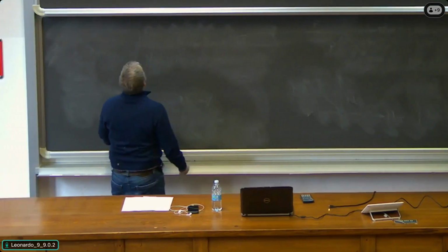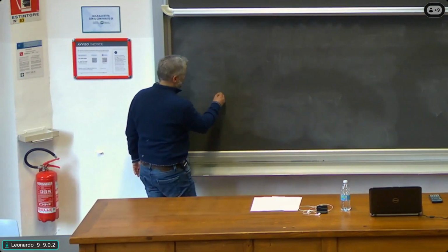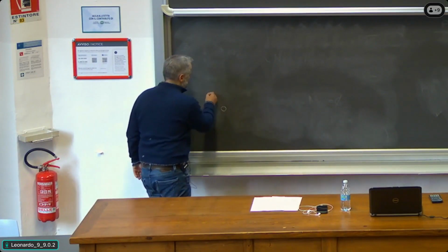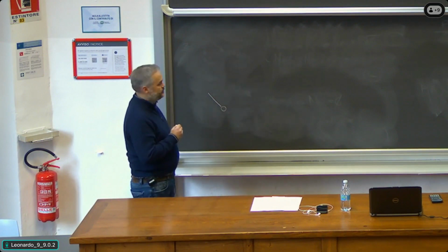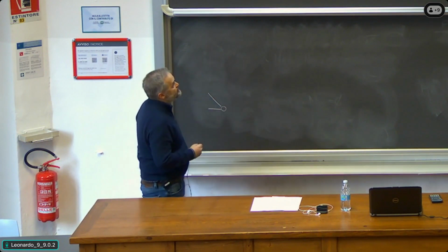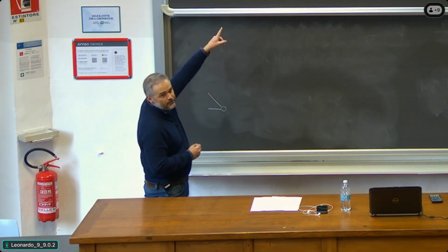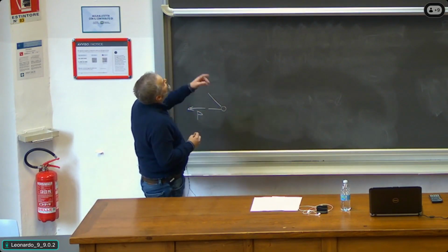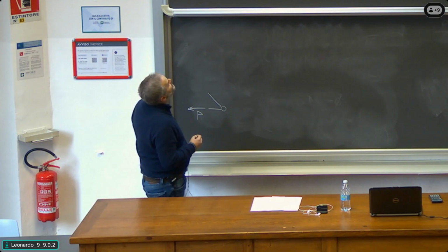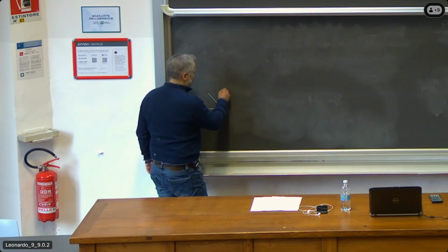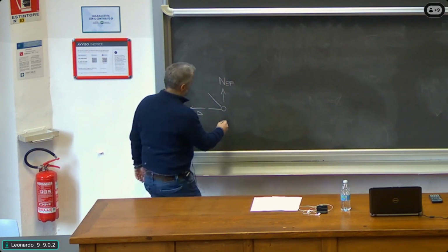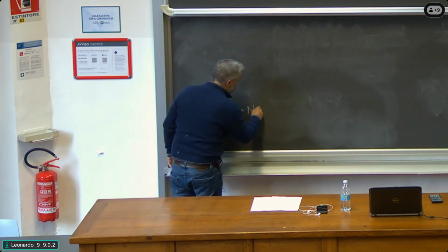So as I mentioned, I am now at node E. At node E, we have a diagonal member which is unloaded, a horizontal member which is C, and we see there it's subjected to a tension force which is P, so I will put it directly here. Then we have a vertical member called EF, and therefore it has a force which is NEF. And then we have a horizontal force which is NEG. Okay?